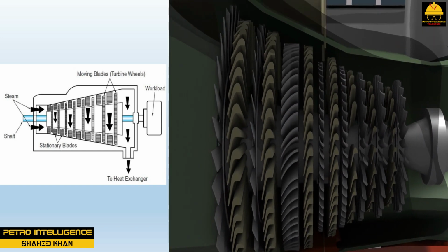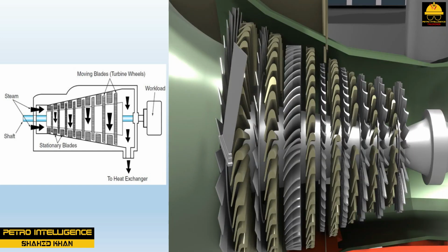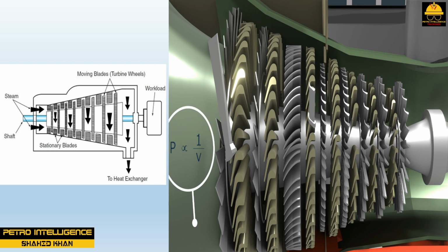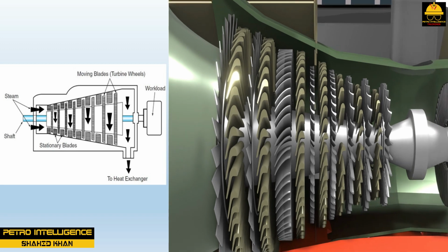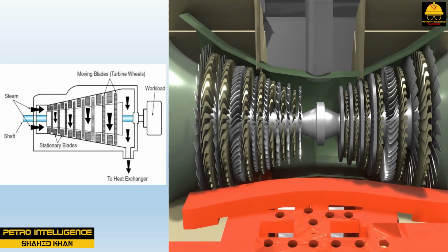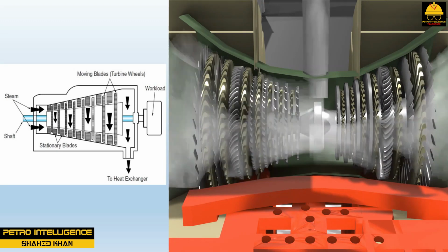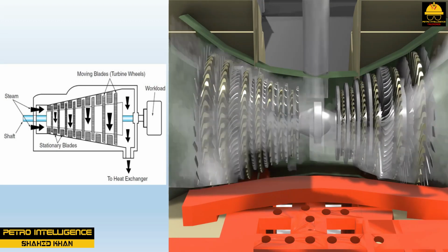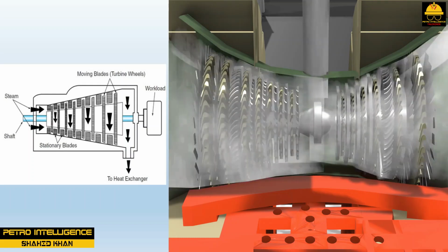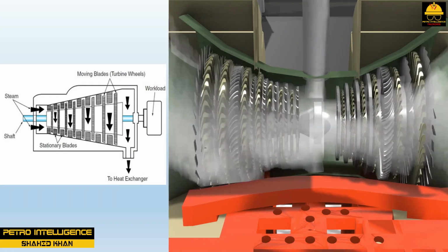As the steam passes through alternate sets of fixed and revolving blades, it constantly expands as it moves along. The rotating paddle wheel is attached to a shaft, and the blading and shaft together make up the rotor. Impulse or reaction movement occurs as the steam strikes the rotor, converting the steam energy into mechanical energy. The amount of steam energy needed to perform useful work depends on the pressure range through which the steam expands.